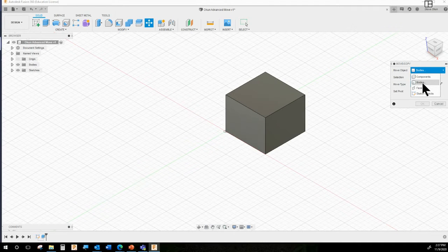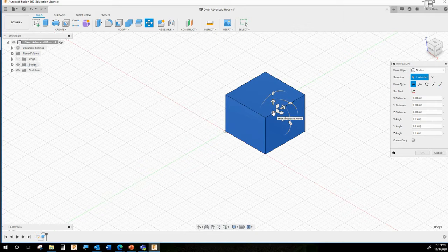But mostly you're going to be moving an entire thing, just like you did in Tinkercad. You're not going to be resizing it, which is really what moving a face would do, or changing a sketch object. So generally you'll be using bodies. Make sure your dialog box says body right now, and then go ahead and select your box to tell it that's what you want to move.